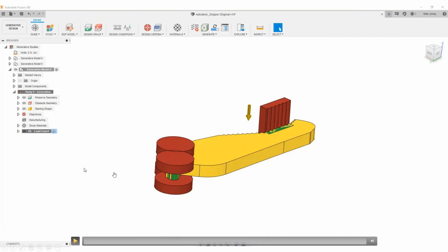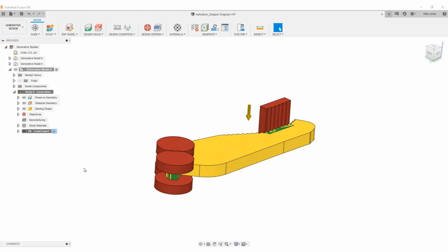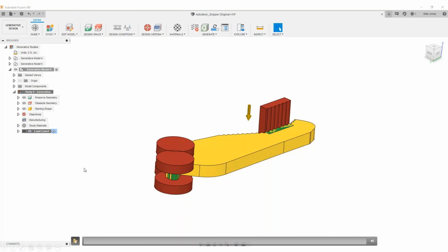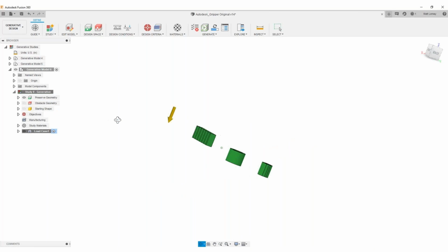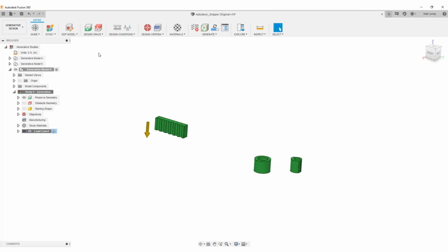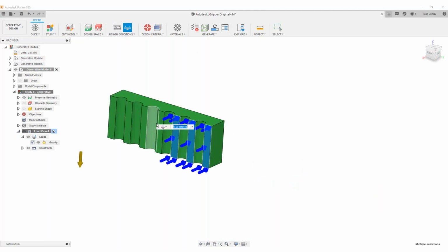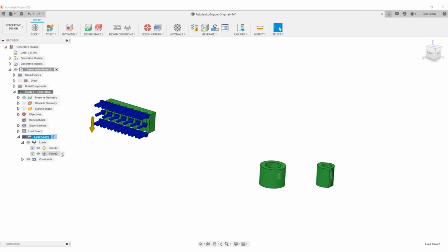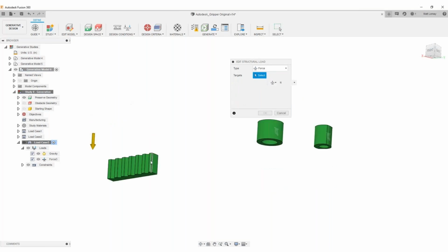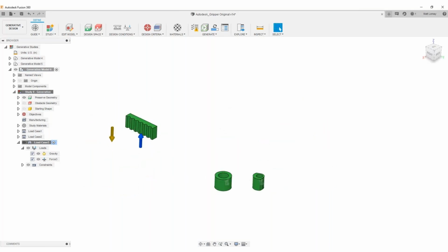So now, instead, what I'm going to show you is really specific to the generative design environment inside Fusion 360. So now I'm going to define the design conditions. Basically, I'm going to define the loads and the constraints. So I'm going to define the load configuration that basically represents the loads that will act on this gripper while the robotic arm is operating.